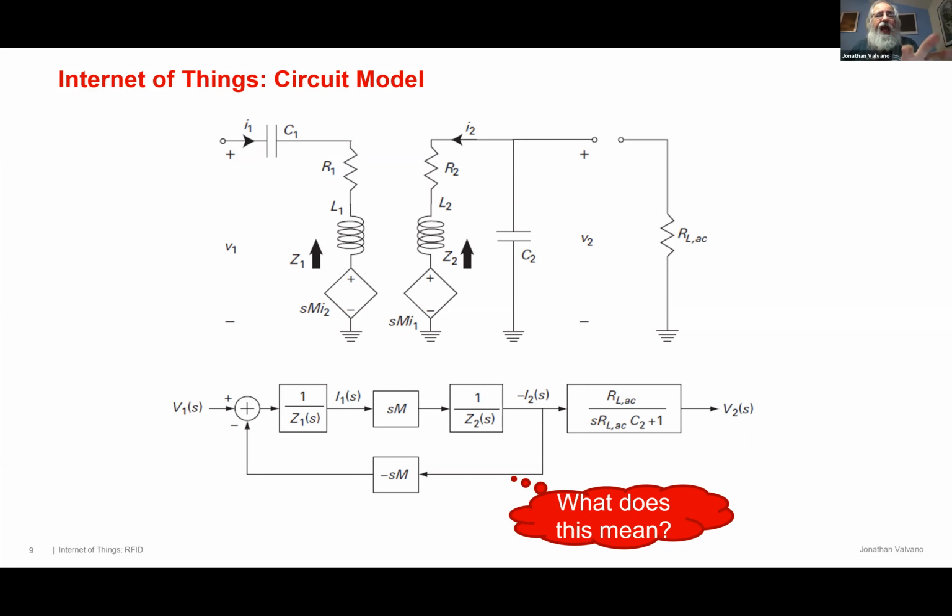We will physically add capacitors to this circuit, but the resistor R1 is not actually a physical thing that we added on purpose. R1 is the resulting impedance because there is a wire there. Because the coil is made out of copper and the copper has a length, there will be a DC impedance to that coil.